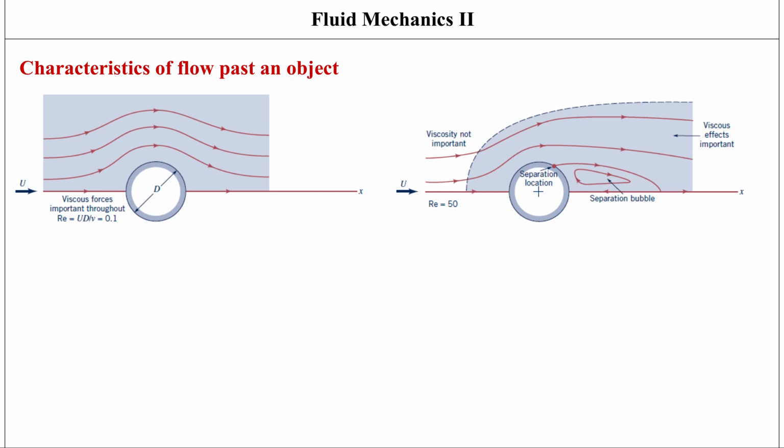So you've got flow separating from the body at the separation location, which is, let's say here. It could be any point on this cylinder, and these are called separation locations. So this flow starts separating from the body at the separation location, and the fluid inertia then becomes important. At some location on the body, like I've said, you've got a separated flow, and then this fluid has so much inertia that it cannot follow this body, this curve, and the fluid can't curve back on top of it. So that means the flow is going to go something like this in this direction.